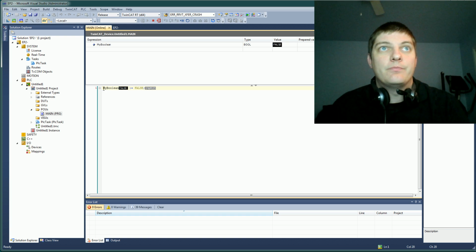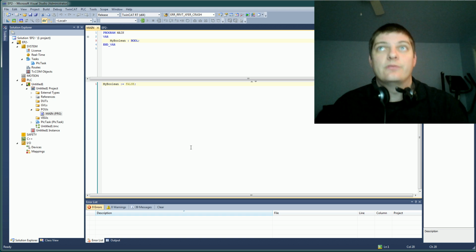So you can set breakpoints here, you can do all kinds of good stuff. I can stop the PLC, I can start the PLC. So that's about all I really want to cover, other than actually you can also set these. So I'm setting this actively as false, so I can either write them or I can force them. So if you force it, it's stuck true, although in practice I don't particularly care for this forcing of bits here. It does weird stuff. But anyway, that's basically the overview of this entire IDE.